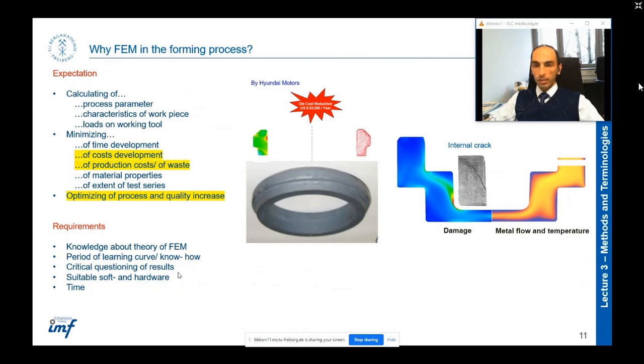It's really beautiful, full of colors, and you can see the process inside, but the results are not useful. First you should think about your model, how to model it and simplify it in a way that does not harm the result in your area. Then run the simulation, then calibrate it with the experiment, and then you can obtain useful results.